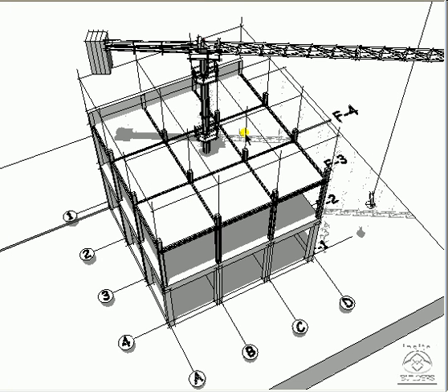The erection of steel on the 3rd floor, or the 2nd level of steel, is a lot more straightforward. This follows the traditional practice of all columns up and then all beams. But note that the columns have a pattern of erection. First we go along the back wall on the 0 lot line, then this outer wall, and then the interior columns.